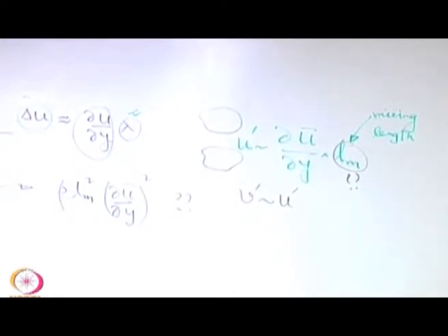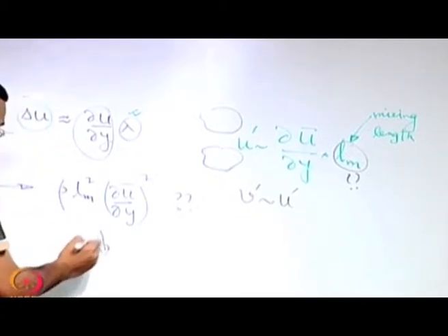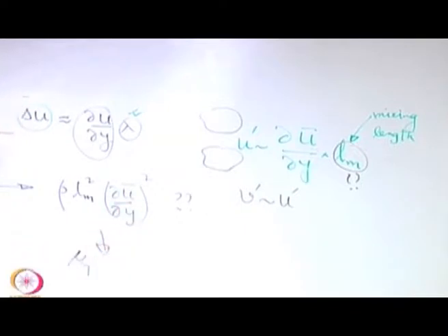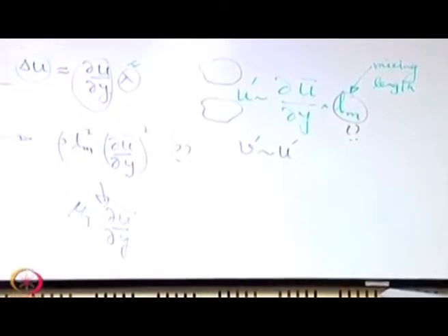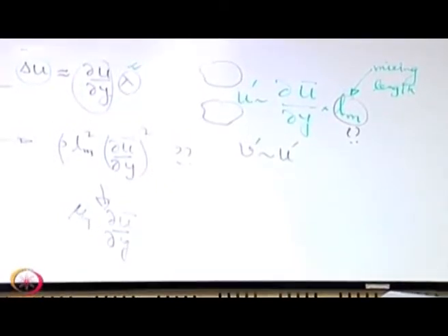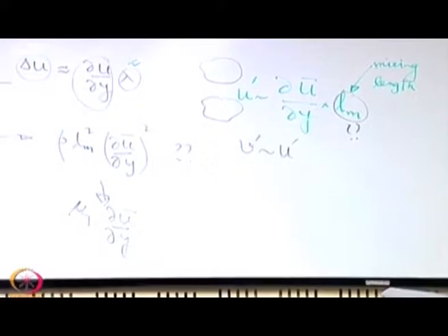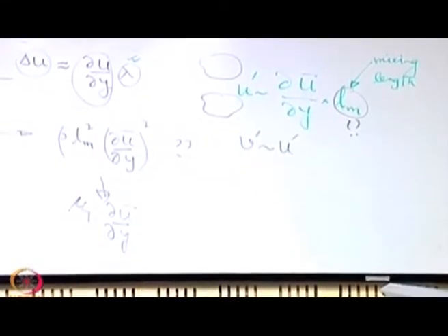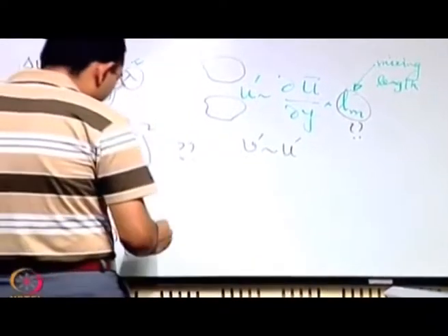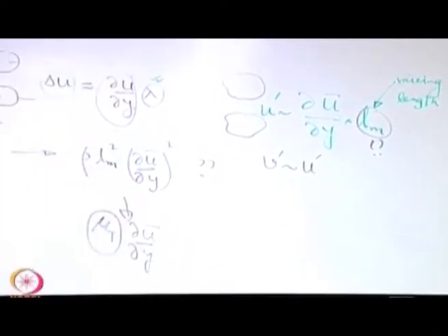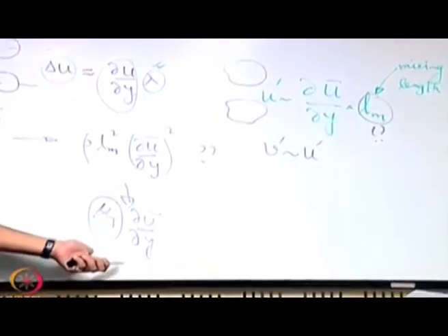Remember, at the end we want to write this term eventually as some equivalent viscosity, turbulent viscosity we called it, into the rate of deformation. We are just taking a 2-dimensional example where you have fluctuation components u prime, v prime. Now if you want to do that, one of the things we concluded is that this mu t has to be positive.